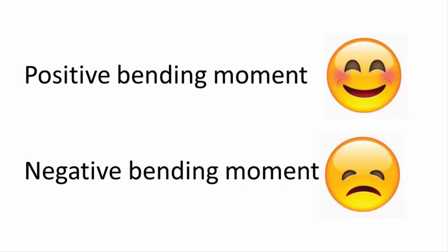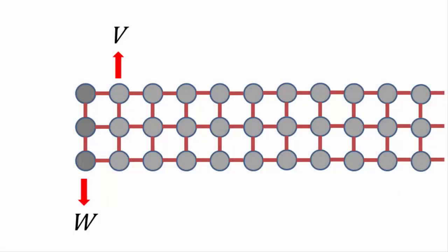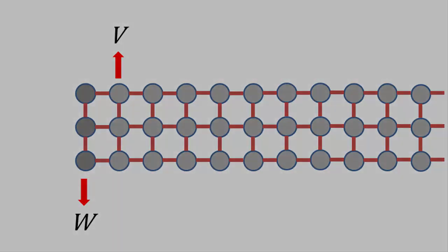The last characteristic of bending to consider is what happens to the materials that make up the elements during the bending. From the video on shear, we saw that an applied load can cause the vertical layers to slide from each other and the materials to induce a vertical shear force to oppose it. But there's also shearing that occurs along the length of the beam as well.